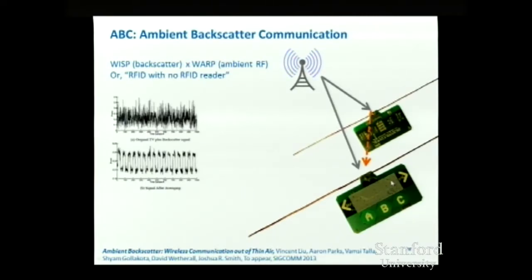Now we've done a couple of demonstration applications here. We built these capacitive buttons onto this one, and there are a couple of LEDs on here. So the first application we implemented was a payment type application. So let's say each one of these is a card with maybe some stored value, and I want to transfer some of that value from one card to another. I swipe the finger across. It backscatters a message to the other one. If it's received correctly, and this one we just have it checking a CRC, it flashes one of its other LEDs.